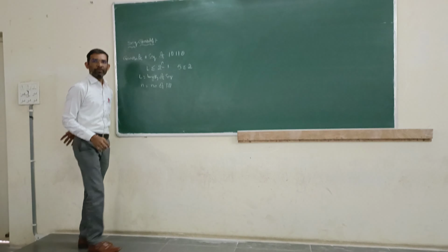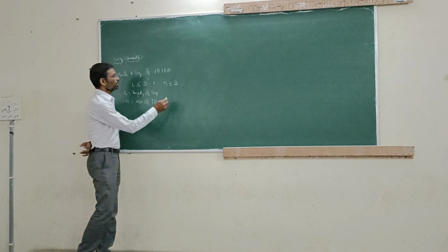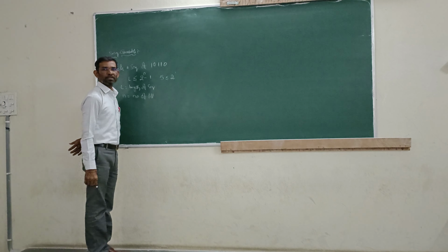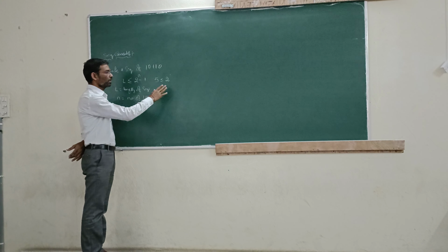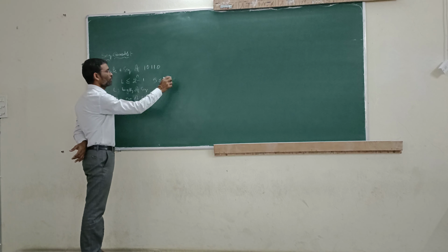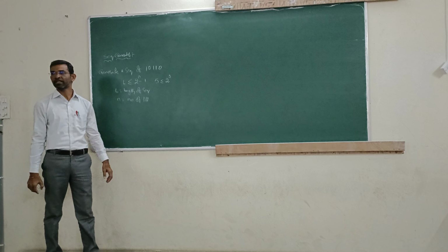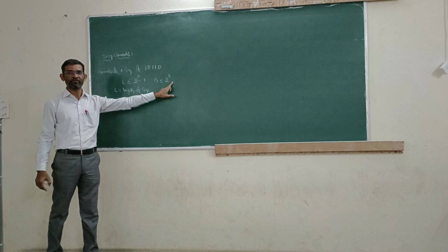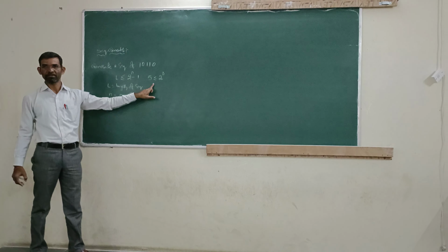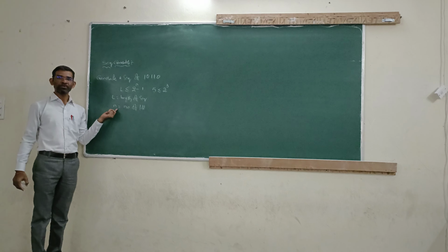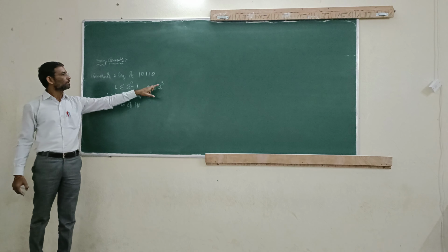In which cases is this condition going to be true? For example, if I take n equal to 1, we get 2 to the power of 1 minus 1, which is 1, so the condition is false. So I am going to take n equal to 3. 2 to the power of 3 is 8, and 8 minus 1 is 7, so in this case the condition is true. Is it clear? So the minimum number of flip flops we have to use is 3.